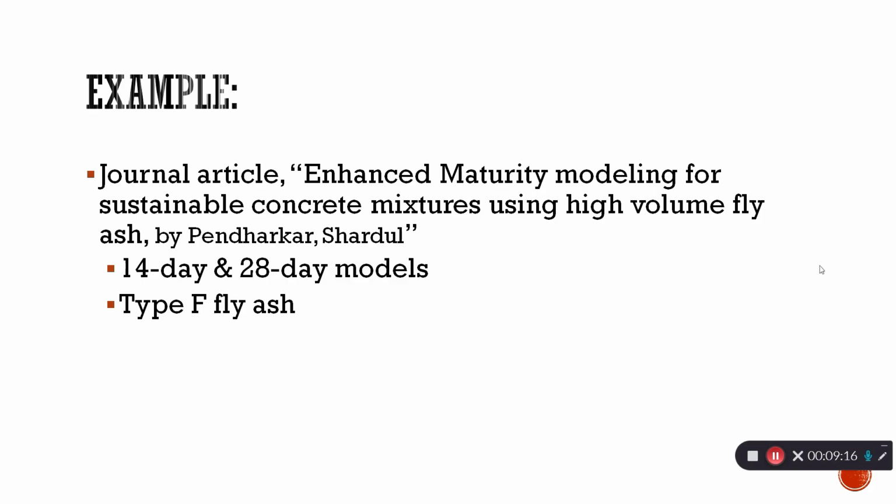The compressive strength of these concrete mixtures in the 14-day maturity models for fly ash type F show improvement in estimating the in-place compressive strength. The setting time approach showed encouraging results and showed that this approach could be used for developing prediction models. The 14-day data consistently provides lower prediction errors than the 28-day models for high-volume fly ash concrete mixtures. Strength development rate in concrete slows down from the 14th to the 28th day, so 14-day data could provide more accurate strength predictions. This can lead to less testing.